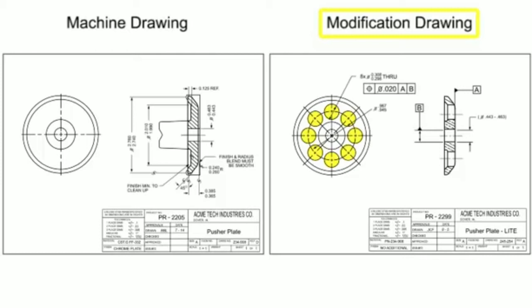Only the dimensions or other information required to alter the part into its new configuration are documented. Modification drawings also incorporate mandatory changes. For example, safety, reliability, or application extension into existing delivered equipment. This type of drawing can also be referred to as a make-from drawing.